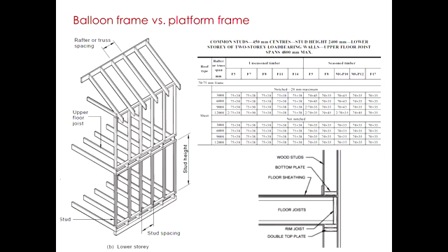You don't really need a scaffold if you're working at the ground level. And once the ground level and the first floor are completed, you can actually work on it to develop the second floor. So this is an evolution of the original balloon framing patent. All right? But I think it's important that we know that we're coming from heavy timber framing, and then we move to light timber framing, what you see sometimes in old American movies, and then to platform frame.